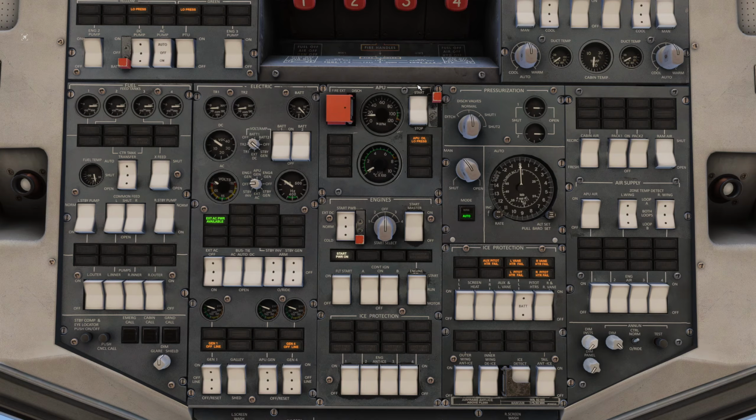How much does the RPM have to show, the value? Typically, you'll want to see the APU RPM stabilize around 100% for normal operation, and the EGT should be within the acceptable range. Once you see that, we can proceed with the next steps. Okay, wait for it. Sounds good.